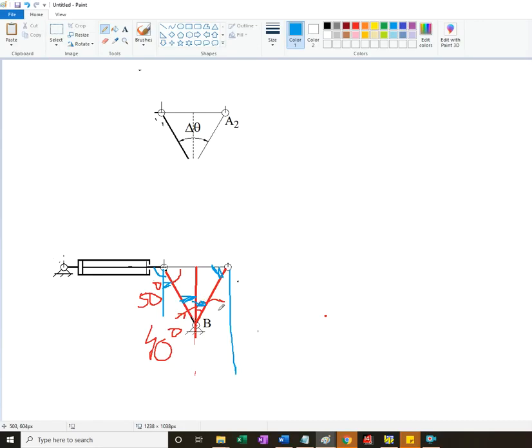So these properties ensure, again, that the way we drew it, we made this construction, ensures that I indeed get the angle of swing that I want for L min and L max, and also have minimum deviation from 90 degrees of the transmission angle, and that's actually this deviation, it's equal to half the angle of swing. So for 80 degrees angle of swing, I get transmission angle that is 90 degrees plus minus half of this, 40 degrees.